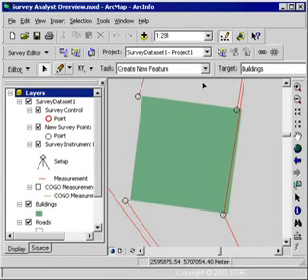So now that I've started the edit session, I've got my building displayed, I've selected and specified the linking and snapping tolerances. I'm going to use the link tool on the survey editor bar to link a survey point to the building corner. I'm going to do that for all 4 corners of this building. And in this particular case, it doesn't really matter the order.